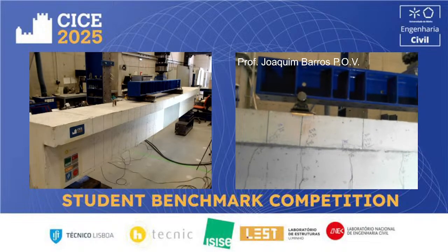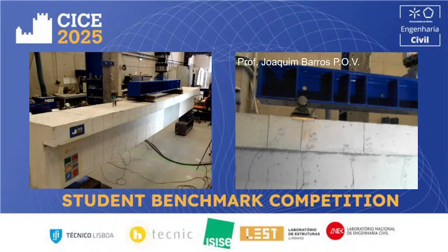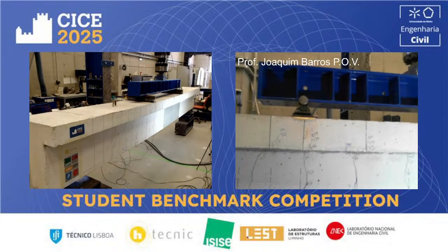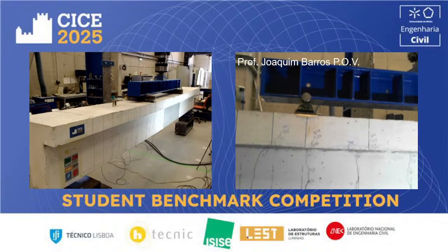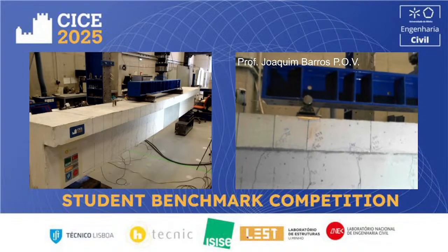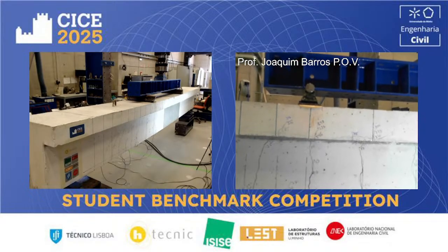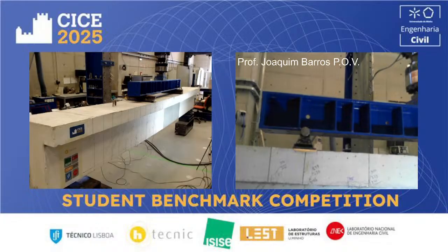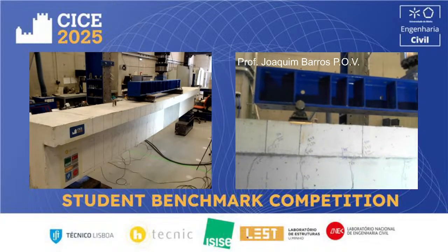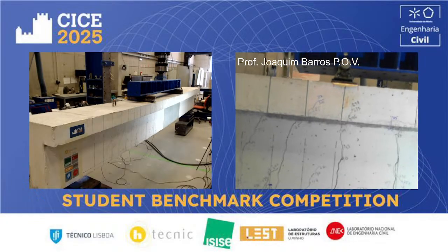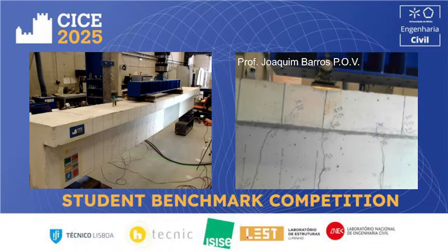So the increment of load is assured mainly, or almost exclusively, by the laminates, with a small contribution due to the hardening of the steel bars, and obviously also the concrete in the top, which is in compression. So crack opening continues to open significantly.